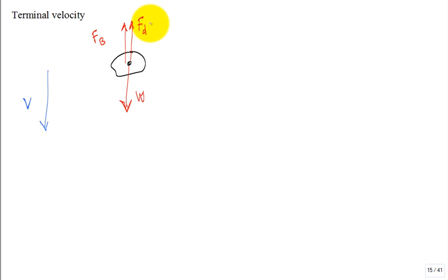Now, the drag force we can unravel. We'll say, hey, somehow I'm able to get the C sub D. I forgot what C sub D is. The name of C sub D is drag coefficient. Multiply that times some A, silhouette area, the projected area in the direction that it's falling through the fluid, times some 1/2 rho V squared. What is that V this time? Well, that's not the free stream velocity, it's the terminal velocity. That's the speed of the object through the fluid.